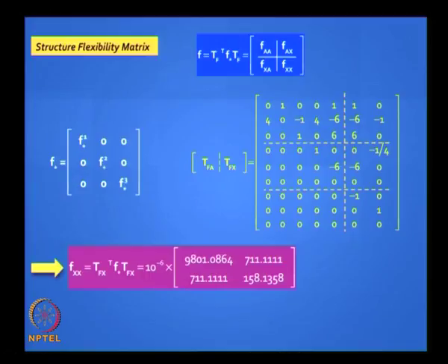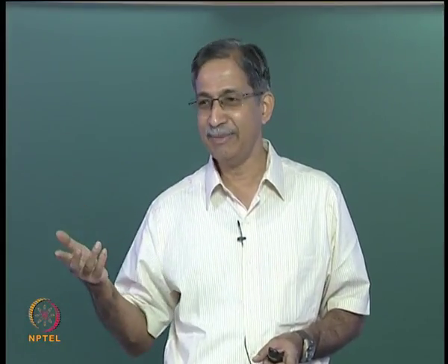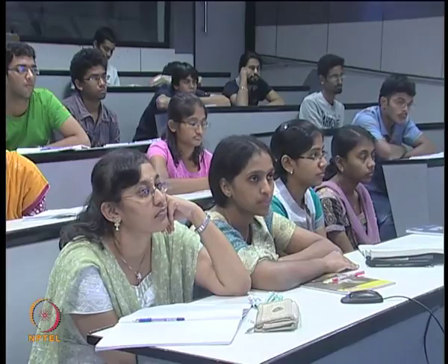Is it clear? In stiffness you do not really have that problem, but in flexibilities you have. You understand, if you have this quantity and you wrote it in decimal format with 10 raised to minus 6, you might write it as 0. So 9800 becomes 0 because you're used to writing by hand, you get tired of writing so many zeros, so you say maybe it's meaningless and you put 0. Is it clear? So be careful, because you need to work with significant figures.